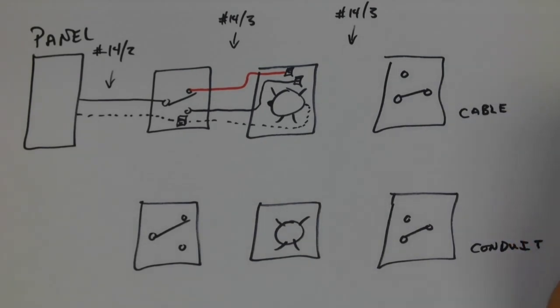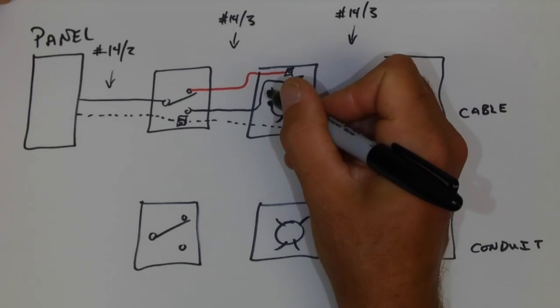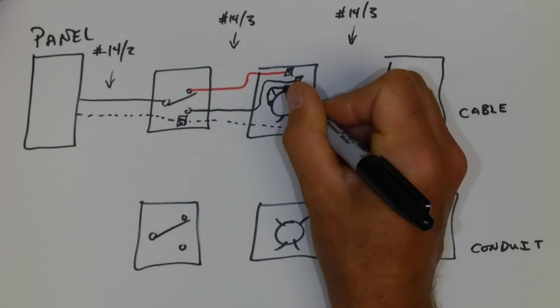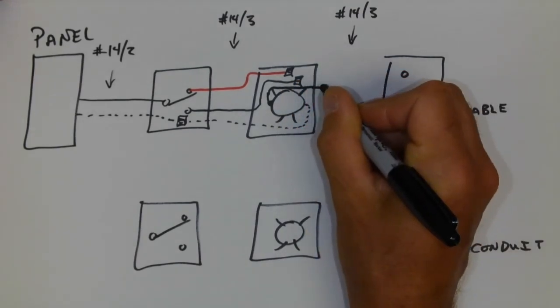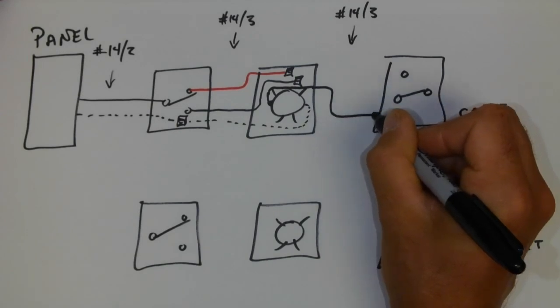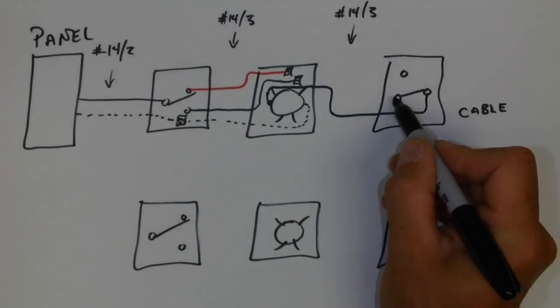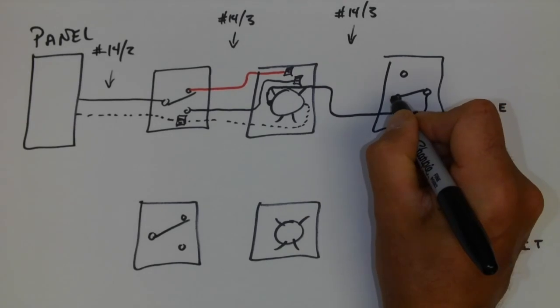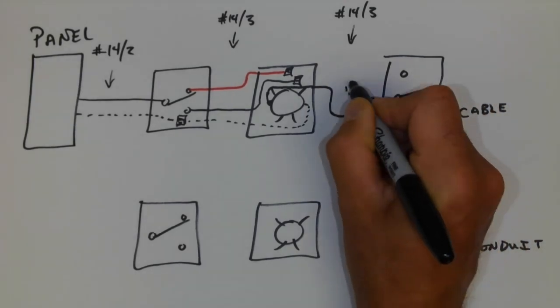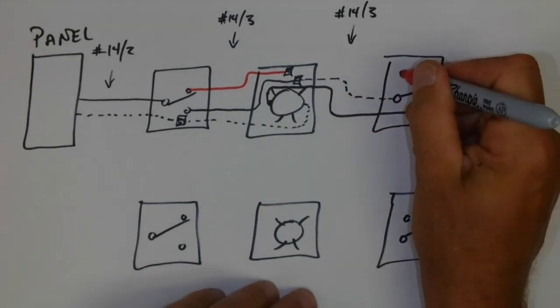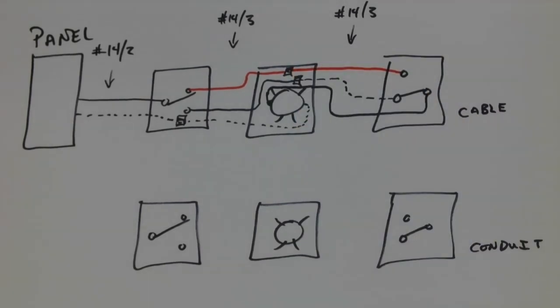So instead, what the code states in section 4 is that we would have to have taken one of the non-identified or non-white conductors as the return conductor and connect it to the common. At this point, then it's up to you how you choose to do the colors of this connection up here. Commonly, people would have done the white up to the black here, and that way the reds were consistent in their coloring.